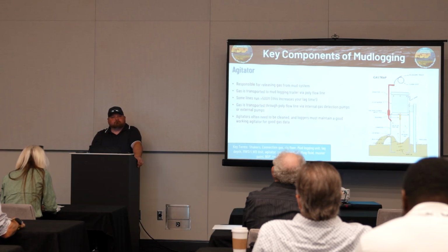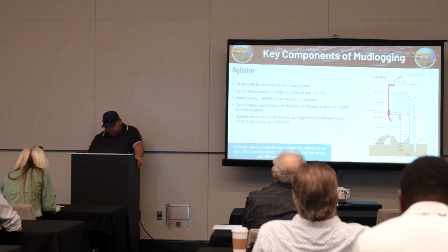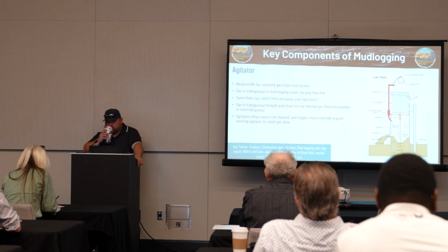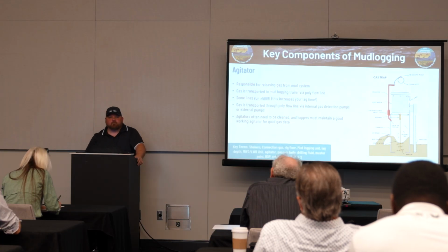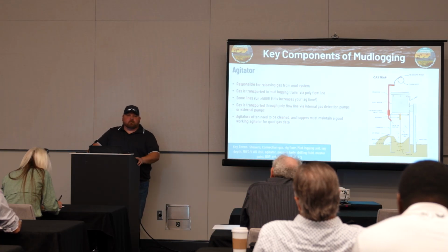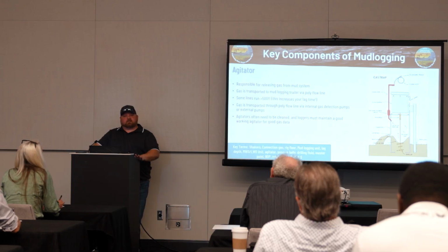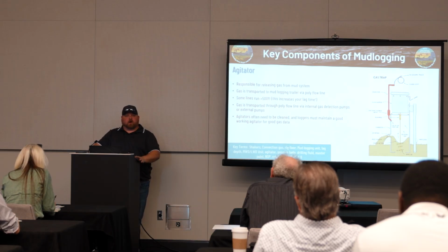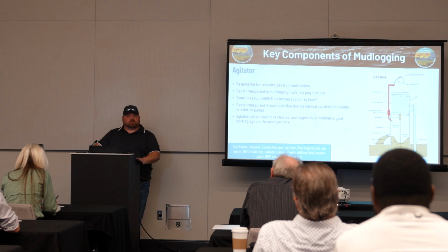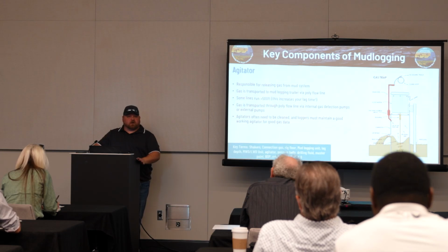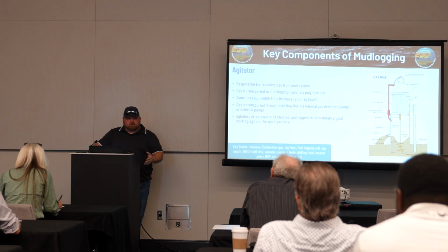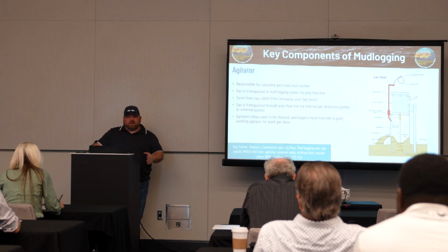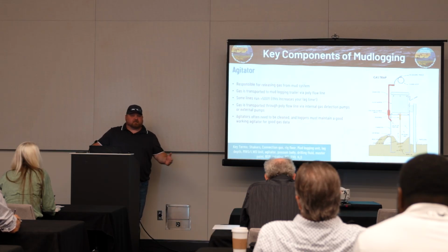Hey Nick, on y'all's talk about polyflow, is that length factored into lag time, or are y'all's calculations just on pump strokes? So it is when it's necessary. Most generally, the pumps used in gas detection systems nowadays are pretty strong, so it's 30, 45 seconds at most. Anything over 500 foot, you really do start to account for it, because you're getting into the minutes at that point.